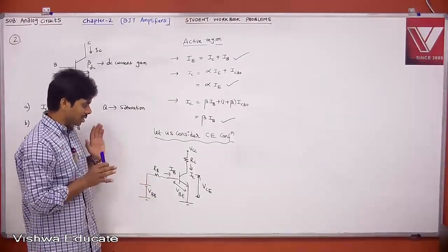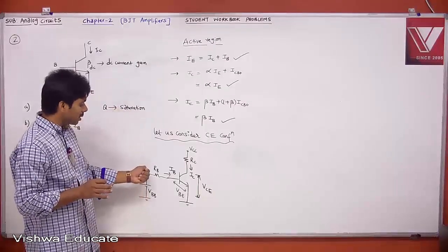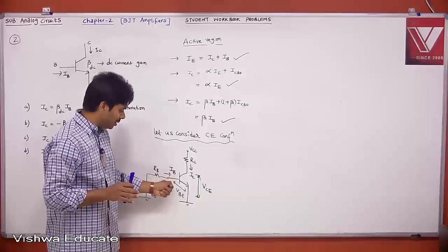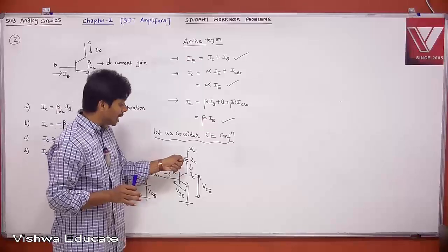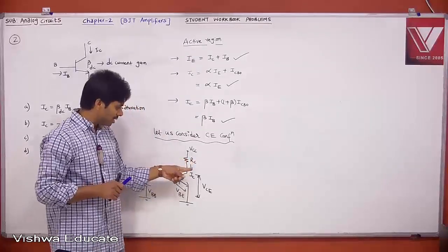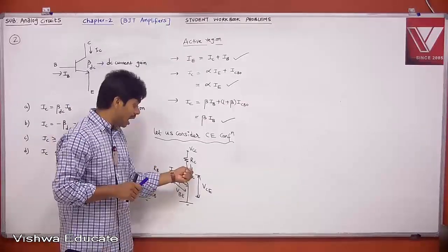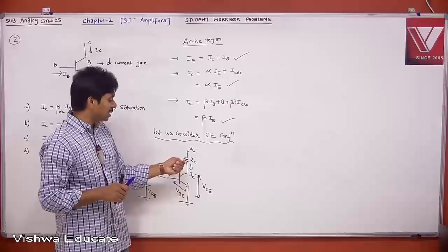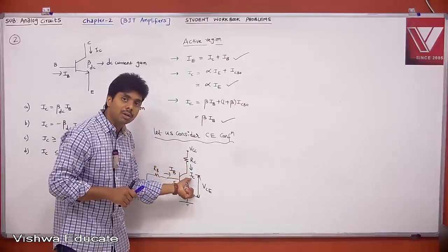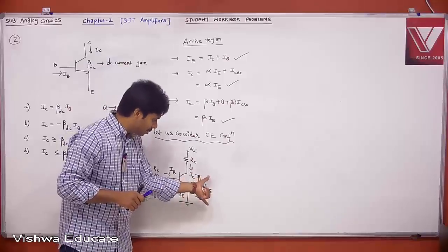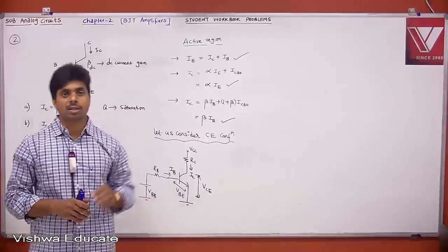This is the equivalent representation. When you put an AC source on top of the DC, whatever AC signal you apply is converted into your VBE change, and that is converted into your IB change. The small signal change in IB will be converted into a large signal change in IC, because the IC to IB relation is current amplification. A large change in IC is a large voltage drop change in RC. Therefore, you have a large voltage change at the output, more peak to peak than the small voltage you apply, so we get voltage amplification. That is what we discussed already.